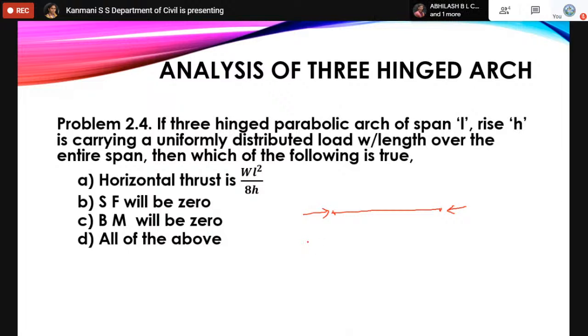See, the compressive and tensile forces we are talking about in trusses are internal resisting forces. That's why we find the degree of internal indeterminacy. So we have to find the resistance. If the loads are coming from outside to inside, then the member will resist from inside to outside like this. So this is a compressive force resistance. That's why we write the force towards the joint as compressive force. The force moving towards the joint is a compressive force. This is the reason for that.